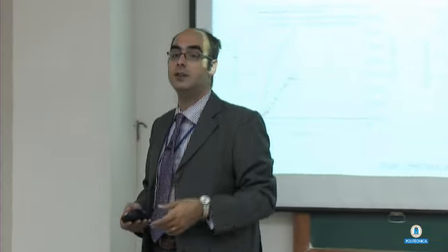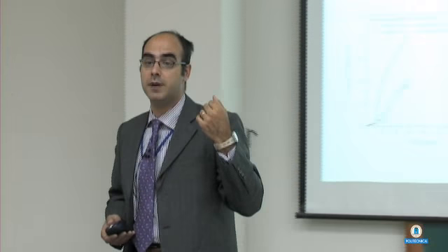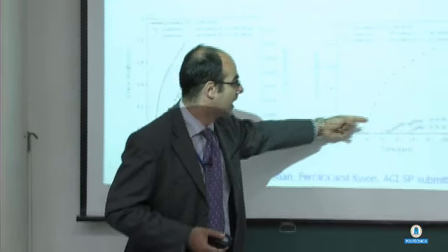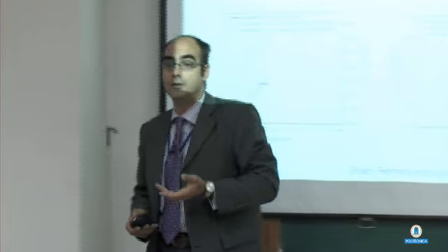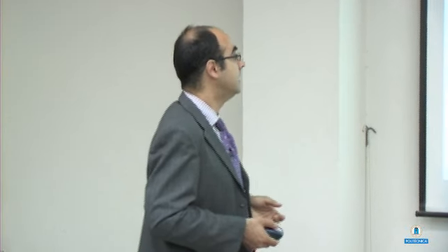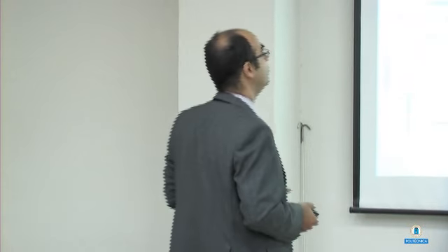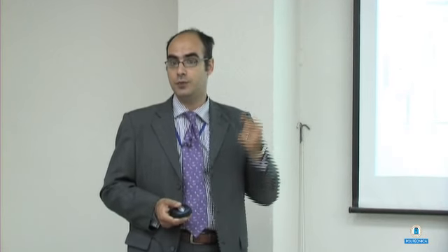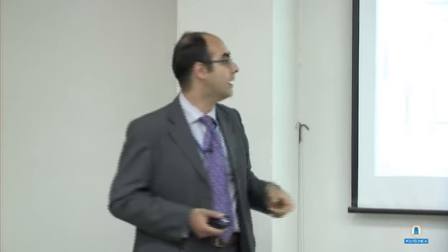which is surely beneficial. Also taking into account what we previously said for self-healing, because these cracks you cannot surely self-heal, being too wide. But cracks up to 5 microns, you can hope that the material will be able to self-heal with the development of delayed hydration products. And the model was well able to capture also the strain in the steel annulus, which was the control to check when the crack starts.